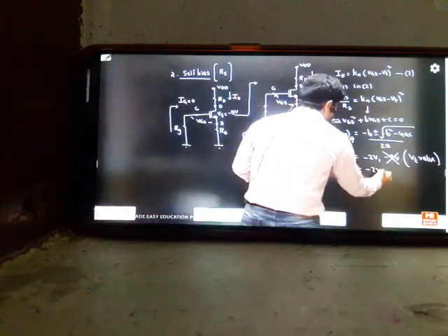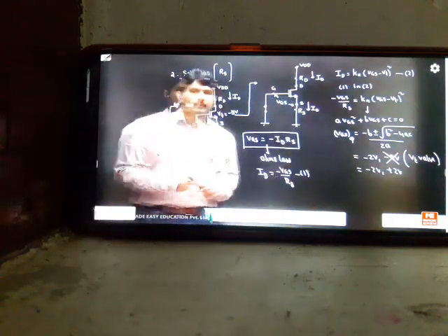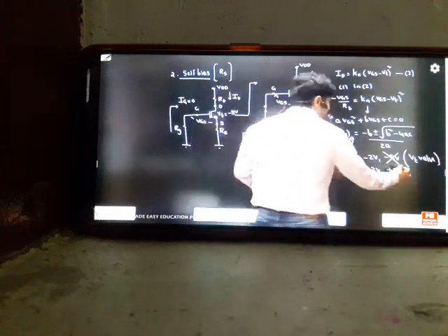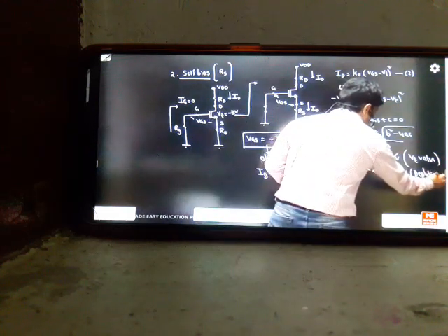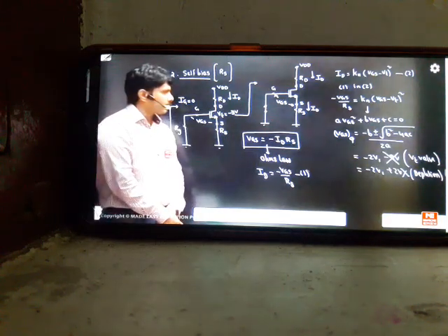And suppose my answer is minus 2 and plus 2 you got. I think for this nothing is required. Threshold knowledge is also not required, because for a depletion MOSFET VGS cannot be positive, it will be negative. It's a depletion type, so for depletion type, VGS cannot be positive. Like that you can tell the answers for the samples. So this completes my VGS knowledge.